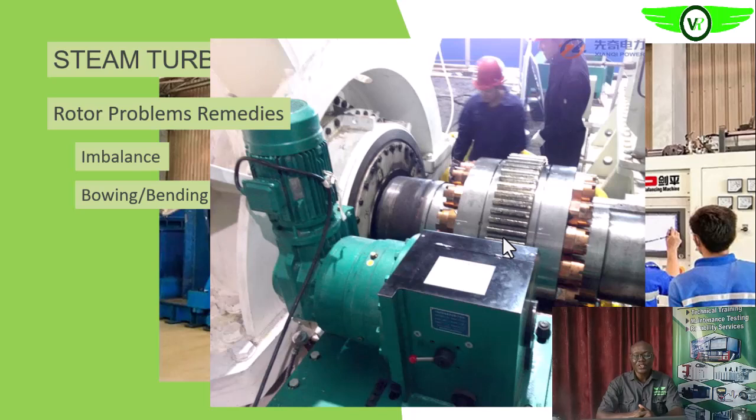Then during shutdown too, after shutdown, remember I want it to cool evenly. We don't want that temperature gradient to develop, to avoid this bowing or bending. The turning gear will be set into operation also. So it will be turning the shaft or the rotor of the steam turbine at that low speed until the equipment is fully cooled.